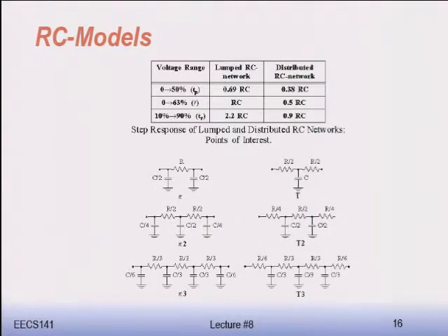And so essentially, this just summarizes, but I think the bottom line is that you're pretty safe. If you look at all these values, it's really only 50%. If you look at the equivalent time constant, the 63% rise time means that the error is 1 over e. But in general, you can argue that the delay is always about half of what it would be if you took all the resistance and put it together in a network with the total resistance and the total capacitance as an RC network.